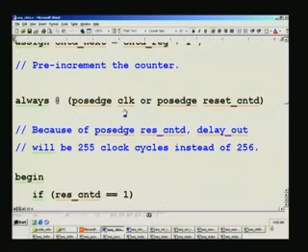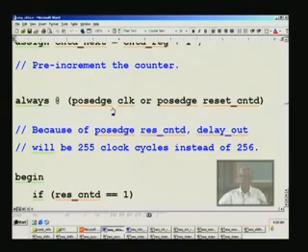We have a positive edge of clock just now arrived, which made the counter 255, and immediately following this, within less than a nanosecond or around a nanosecond, this assign statement of reset control D is making it 1. So what happens if that is 1? Earlier it was 0. So what is put here as a condition is 'or positive edge of reset control D'.